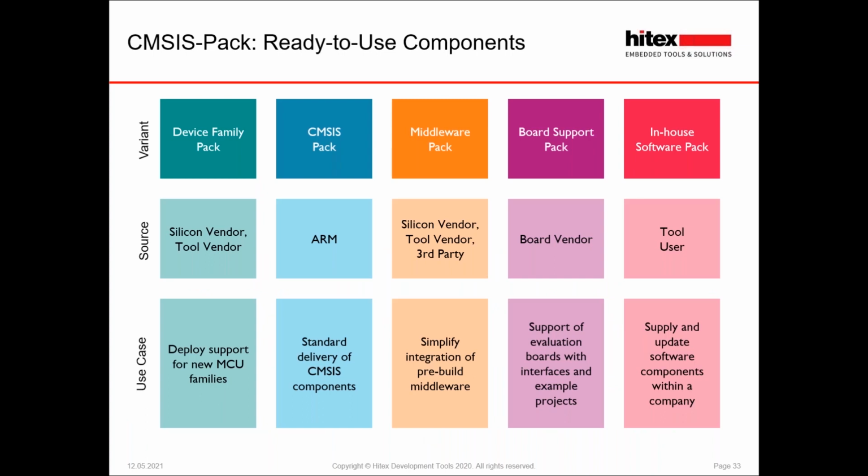Now, once we've generated all of those things, we can start to create a software pack. Originally, a software pack was intended as a means of delivering support for specific microcontroller families. So it has things like the flash algorithms, the startup code, documentation, etc., the specific debugger windows. But it's also used for a number of other things, like deploying the CMSIS standards, other software middleware components, board support packages. But as I say, we can quite easily take any code that we want to reuse and bundle that into a software pack so it can be installed into our tool chain.